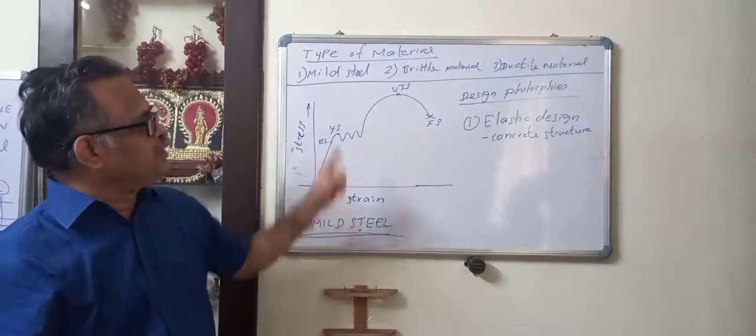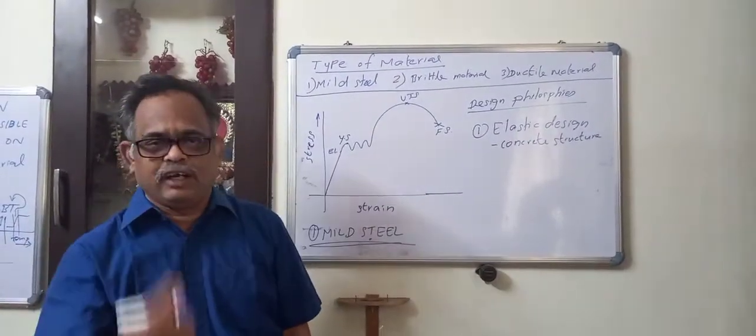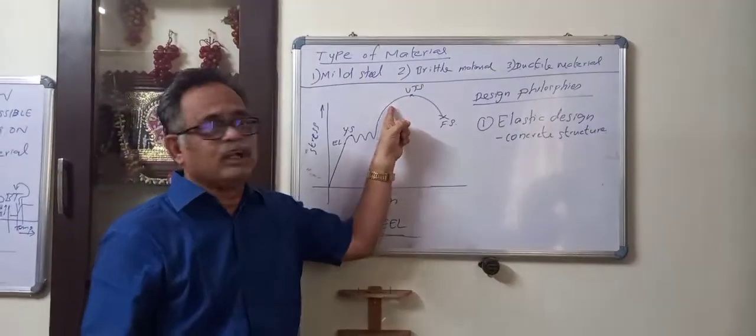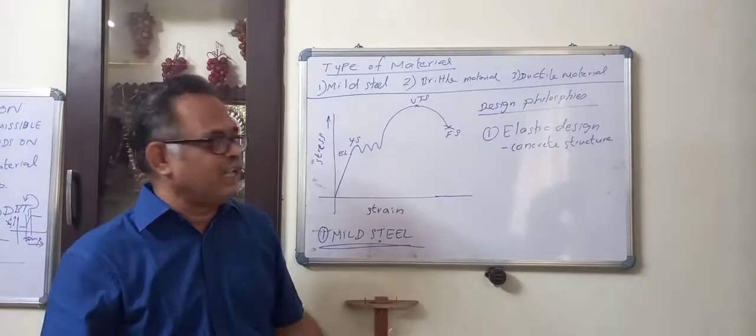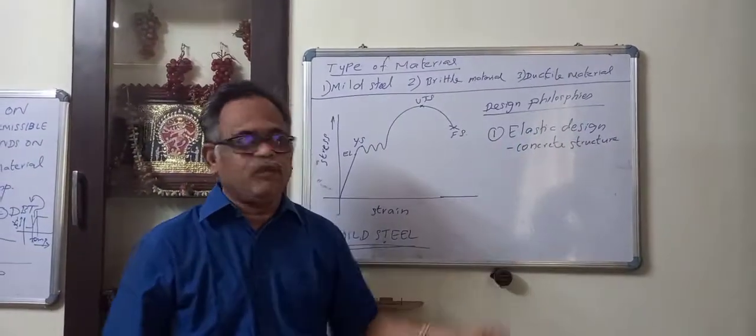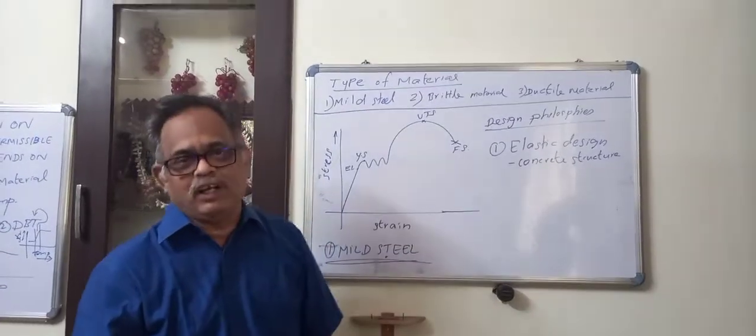So though it is mild steel, for example the reinforcement inside cannot be designed for plastic design. The reinforcement should be designed based on the elastic design philosophy only.